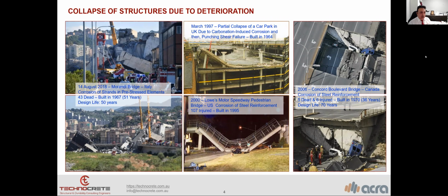The second one is a car park in the UK, where we had carbonation-induced corrosion, and then due to the reduction of the steel reinforcement diameter, we had punching shear failure. Then, as I mentioned, the durability problem has resulted in a structural problem.